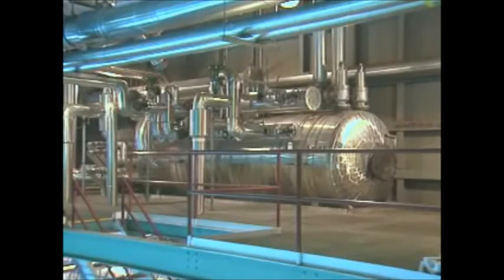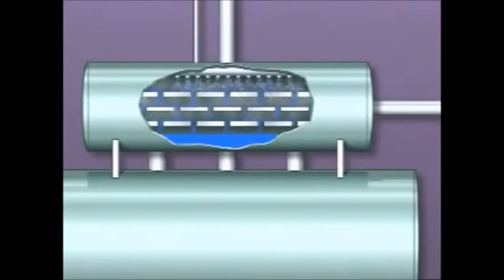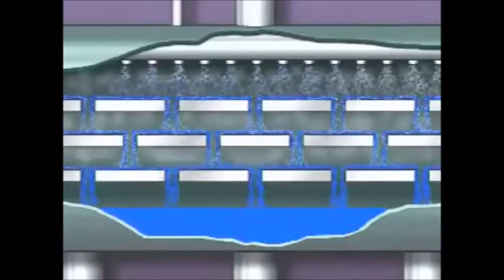The deaerator heats condensate and also helps remove air and non-condensable gases that can cause corrosion. As this cutaway illustration shows, unlike a shell and tube heat exchanger, the deaerator is an open or direct contact heater. That is, condensate is heated when extraction steam and condensate contact each other and mix in the deaerator. As heat is transferred from the steam to the condensate, some of the steam condenses and some of the condensate is heated. This action strips or removes air and other non-condensable gases from the condensate.